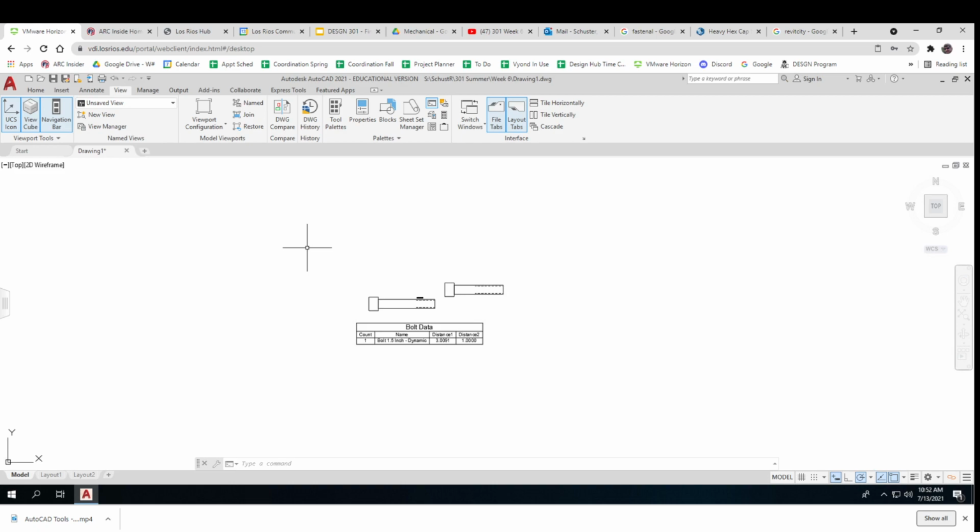And then I'm still not clear. What is the difference between press pull and extrude? Okay, extrude. Because that gives me this weird wireframe thing that just confused the crap out of me. Yeah, so extrude does just that. And if you pull lines, it gives you a surface mesh. And so I couldn't figure out what press pull gives you a solid.